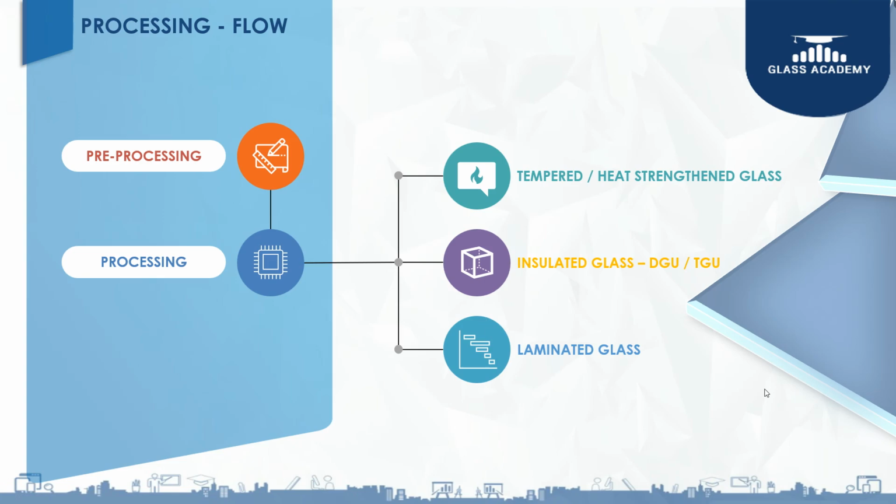Well, tempered glass cannot take the cutting and the drilling of it or the making of holes, right? Because for any patch doors or any patch glazings, the hole is done and the patch size is done, then the tempering is done. Why is that? If I explain the tempering process, that will give you the answer. I'll take this question tomorrow when I start, I'll be explaining it.